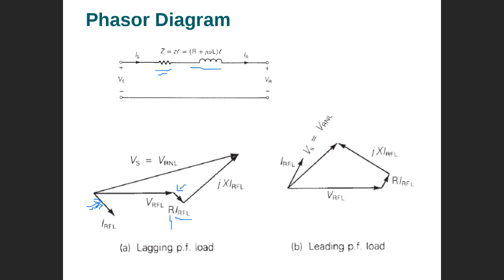And then X. We always mention that X is always higher than R in the transmission line. So X is higher, and the same current which flows on R will flow also on X. Same current times X. X is higher, and it should be at 90 degrees from here to there. Here will be 90 degrees, of this current. So IX is 90 degrees over IR.